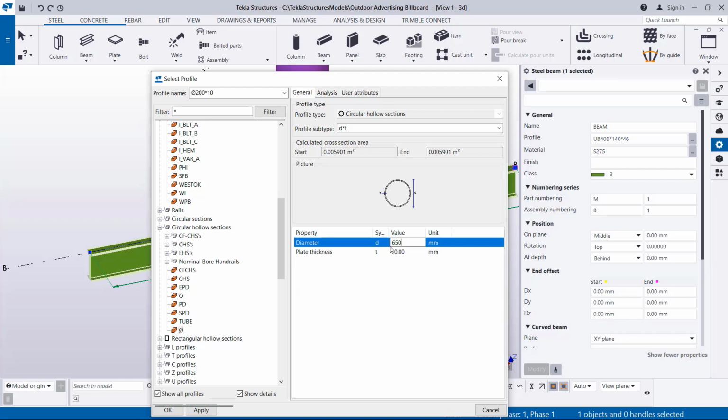Remember, it is rare to get a circular hollow section of this size in the market. So more often, people prefer to buy the plate of that particular thickness, then fold it, bend it to a circular shape, then weld and join until you attain the height of your choice.